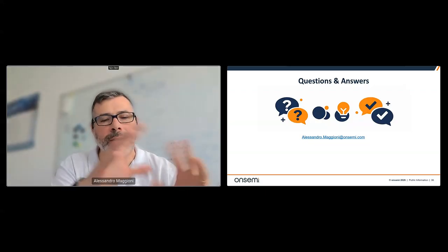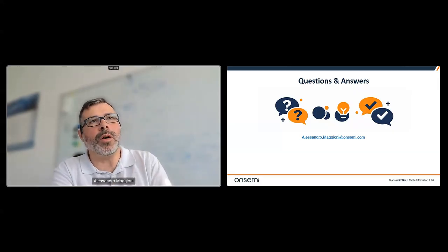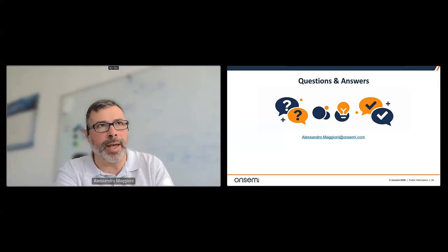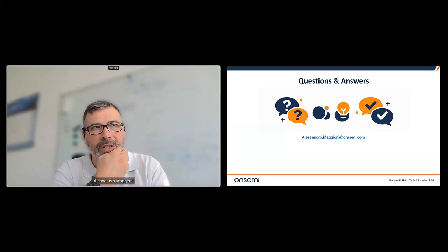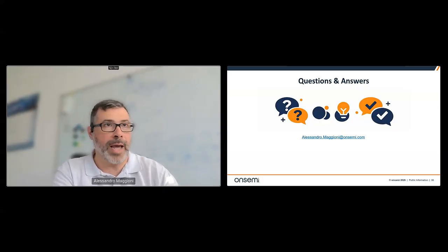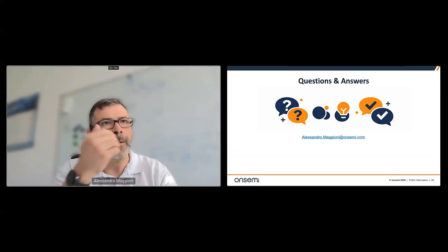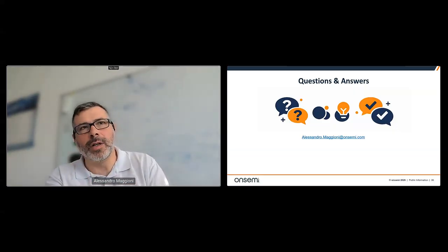Okay, so this is similar to the previous question. Let's say the remote control protocol, or RCP, removes the local microcontroller and its software stack from the node entirely. The central compute issues these protobuf-based messages over the 10BASE-T1S Ethernet to an RCP device, which then drives local peripherals over SPI, an LED driver, a door module driver, or whatever. And then streams sensor and load telemetry back.